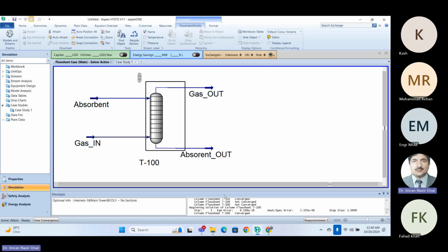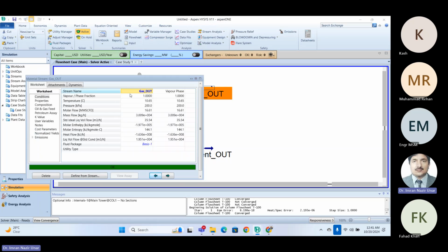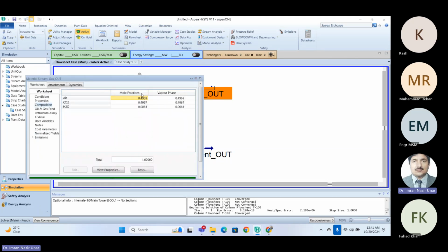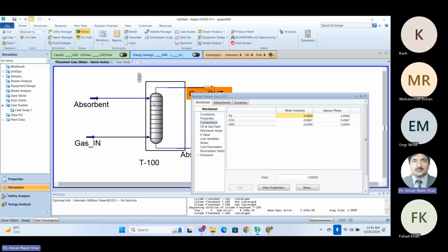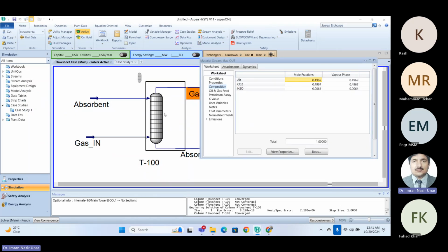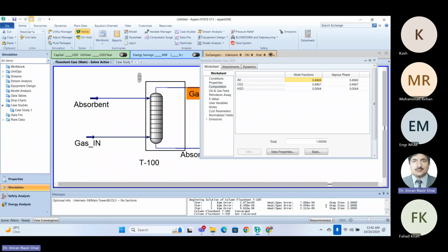So iterations are being done on some mathematical equations like the Clausius-Clapeyron equation in the background, and it says what the possibilities of gas out are, with its parameters like temperature, pressure, and its particular composition. This composition is very important. Raoult's law, Henry's law, and the phase rule, and their derivative forms, are being solved in the background. So iteration is required.